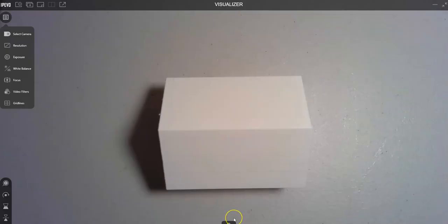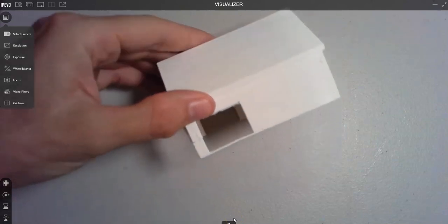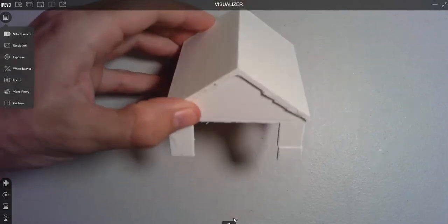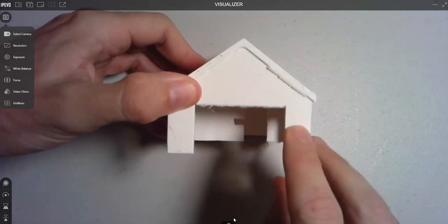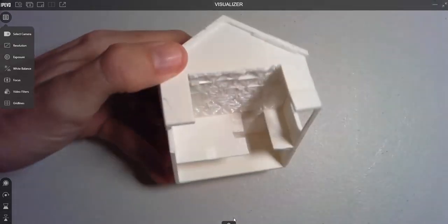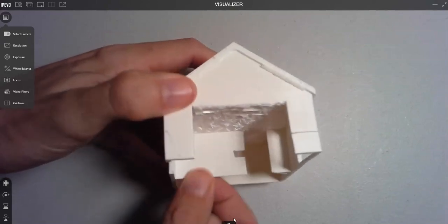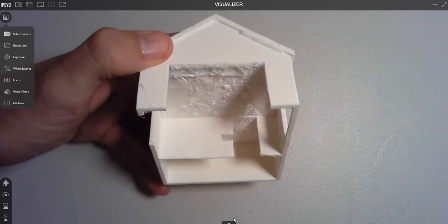Now I've 3D printed one, and I took the windows and the doors out, and I just put some cuts in the side in Revit. Now I could have done a better job with scaling this one because it was a little thin over here on the side, and taking the support material out, I did a little bit of damage to it. You can kind of see that on the inside, but if you scale yours up a little bit more, make these thicker, much easier not to damage. I have some support material up here on top.